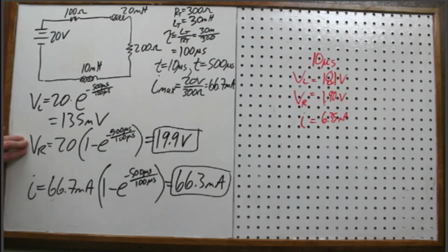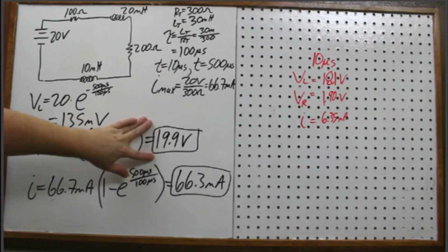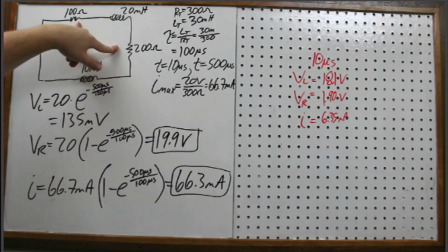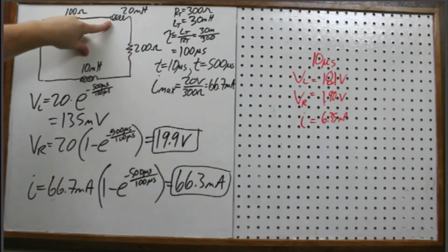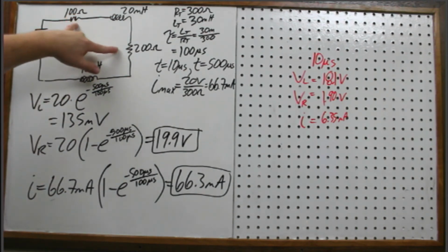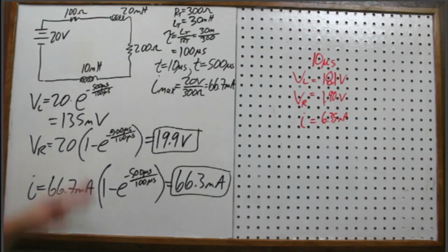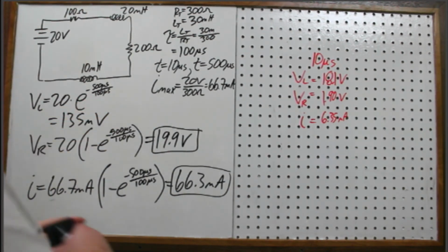So again, these voltages are across both. If I wanted to find out what each individual resistor is, I take this 19.9 volts and then do a voltage distribution here. And I do the same thing for the inductors. I can do this, 20 compared to 10. I still use them in the same way that I would use voltage division ratios. Okay, capacitors are the oddballs. So again, here we've got, circle this.